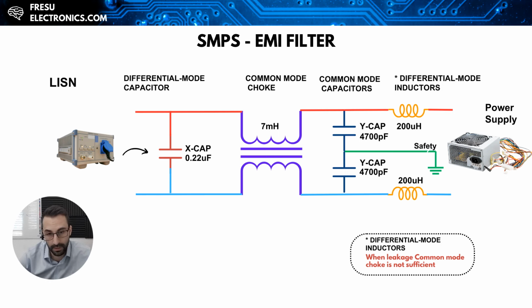This Y capacitor is also special because in the case of failure, it does not create a short circuit, but it will fail open. And this is important because in this way, the phase, which is connected to one side of the capacitor, is not going to be connected to the earth system, which is typically also connected to the chassis and therefore could put the user in a hazardous situation. And similar safety regulation requirements also apply to the X capacitors, which are intended for line-to-line operation.